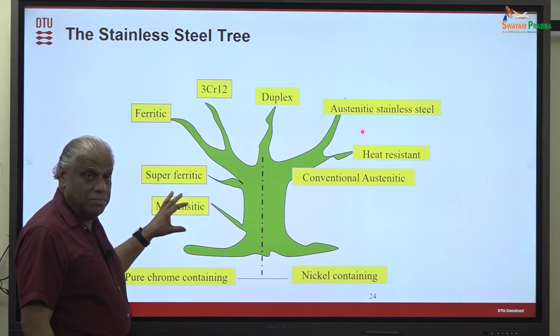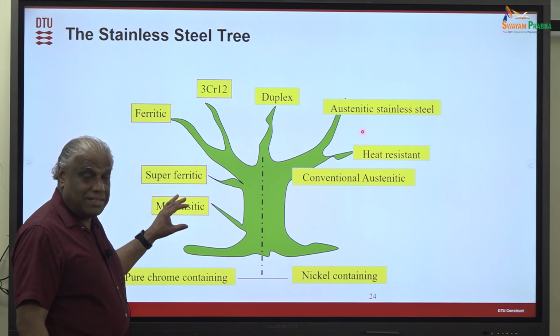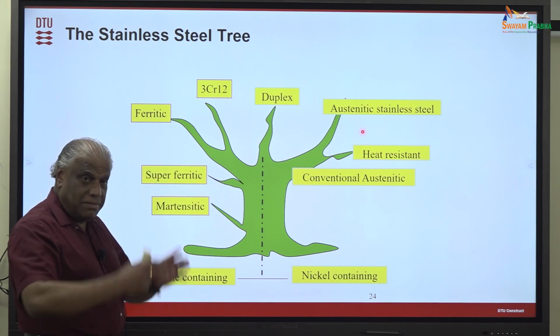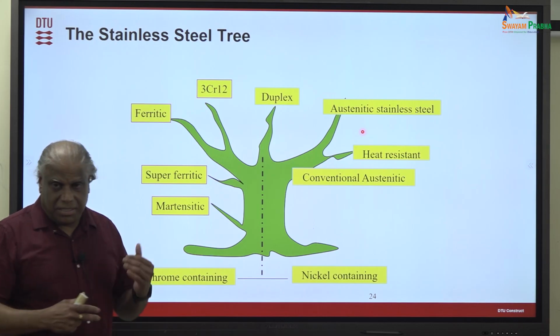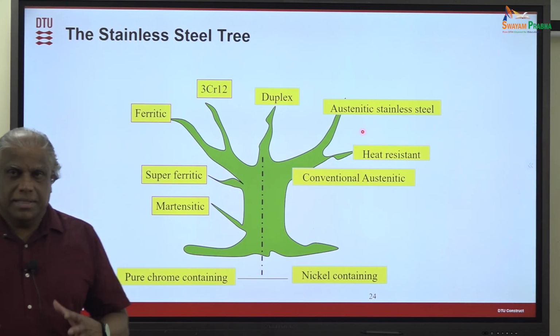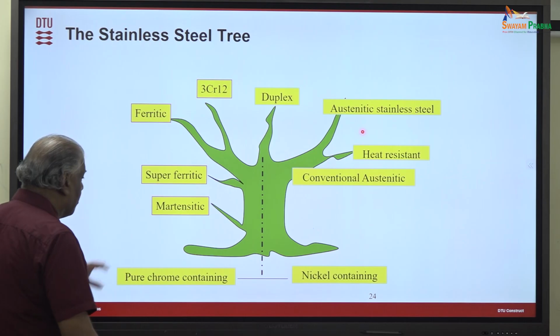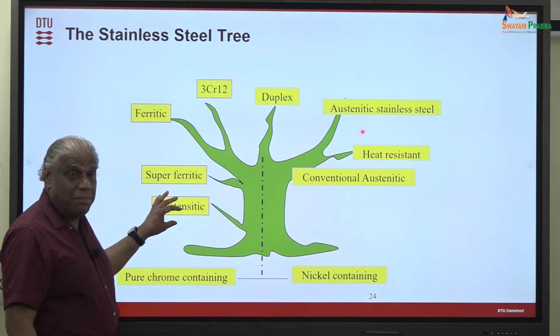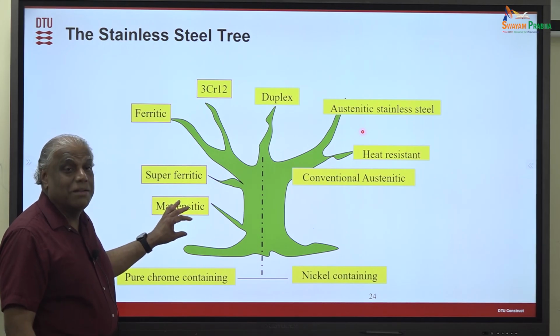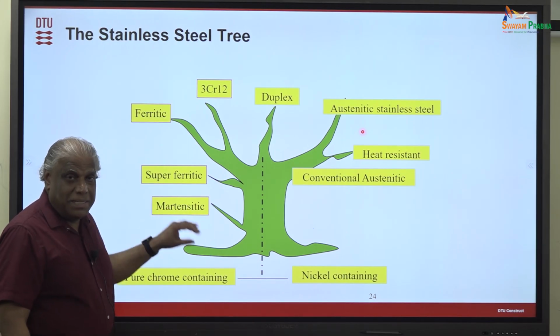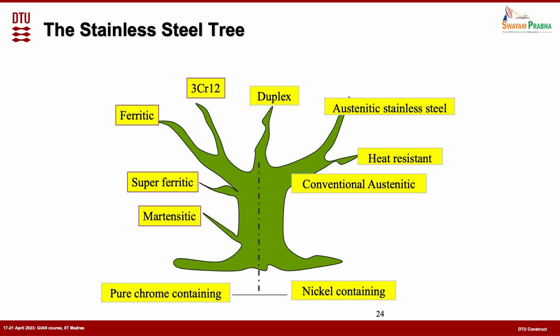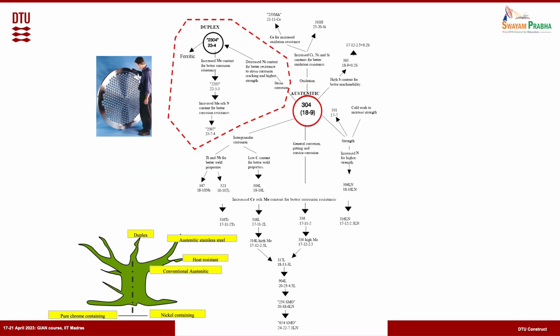we know that it will have a higher corrosion problem. For example, in oil and gas conditions, all the tubing is made not of stainless steel but of carbon steel, and they use it in the martensitic structure, although they know that it has higher corrosion compared to the ferrite-pearlite structure, basically because it has higher mechanical properties. So the mechanical property gives the dominance there, and because of that they use it, although it increases the corrosion problem. But there are some steel materials tailored for corrosion resistance, and there are many things you can look at.